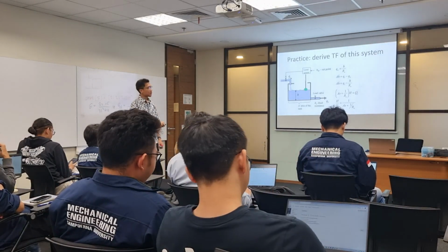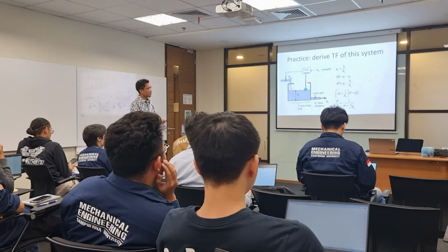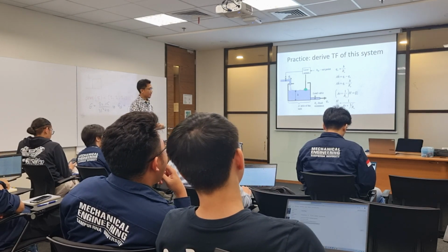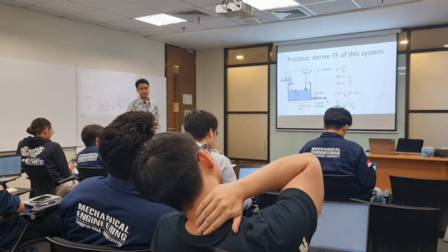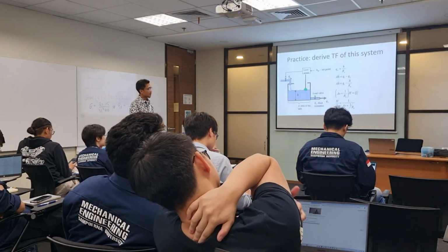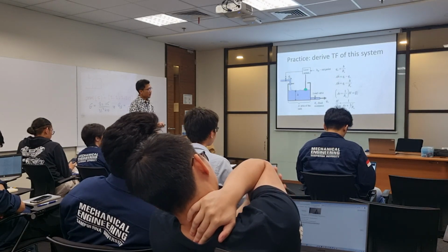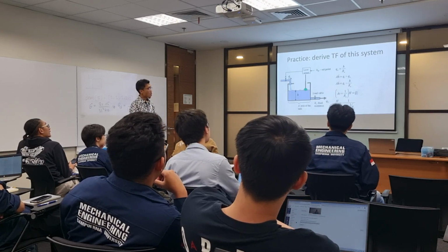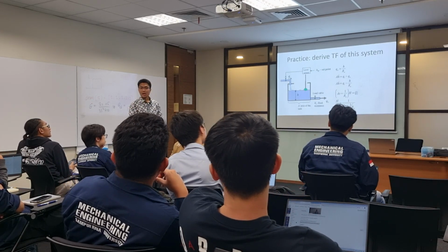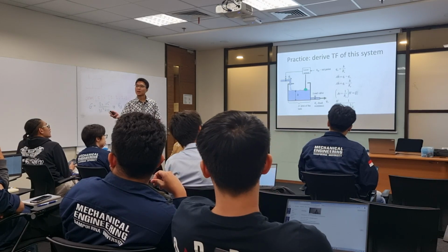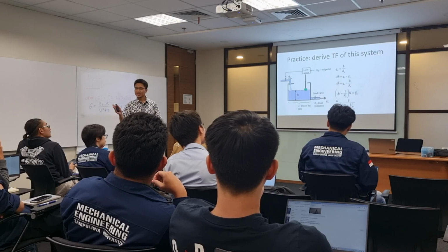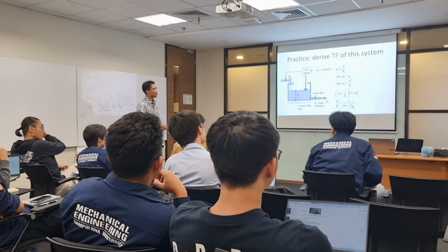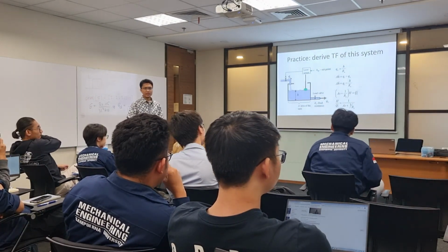Yeah, the first concept that we have here is that the Q0, the output, is determined by the height of the water. Okay, and then there is a resistance coming from the load valve, and then the A times H dot. What is this? The velocity, the rate of change of water. The change of what? The rate of the increase in water height. Increase or decrease, rate of changes. Okay, not just increase but rate of changes. Yeah, correct. So it is determined by input minus output.